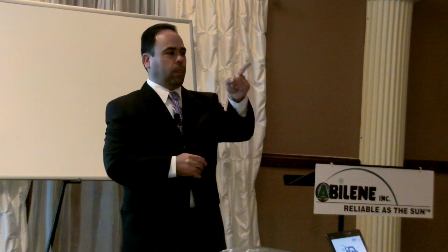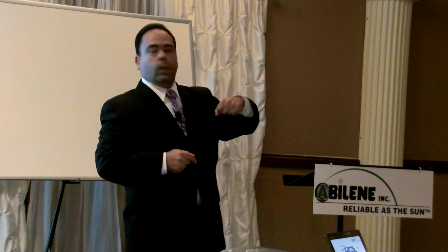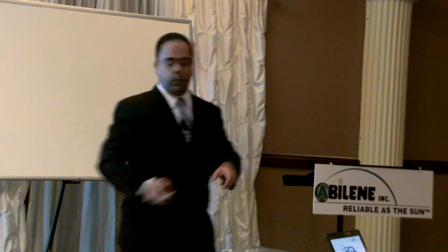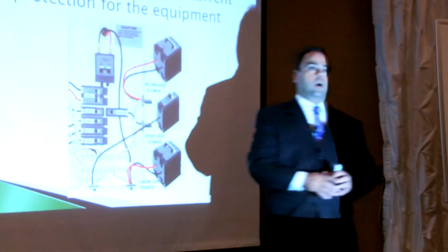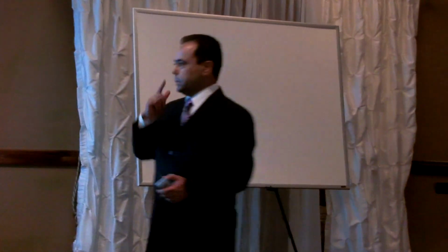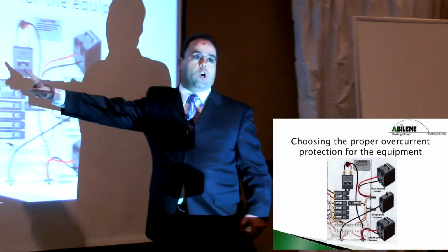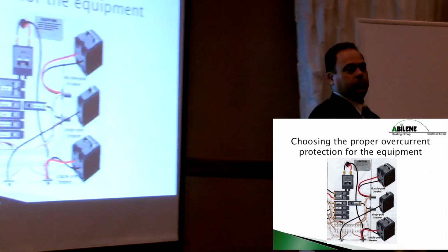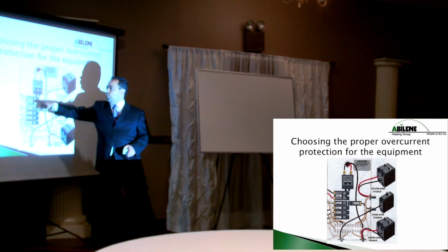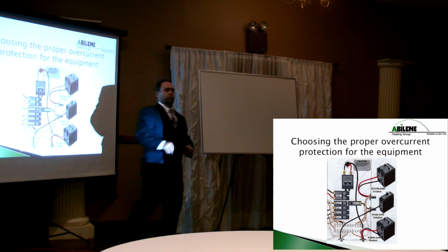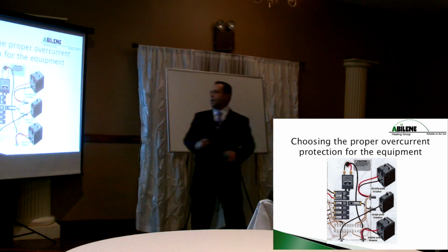You're absolutely right. What he's saying is, if he has a main breaker, like we had in the panel, this main breaker is 100 amp rated, and then this breaker is 50 amp rated. But there's a short downstream of the 50 amp breaker. There are times that this breaker will trip before that one and kill the whole panel. And electricians see that. It's called fuse coordination.